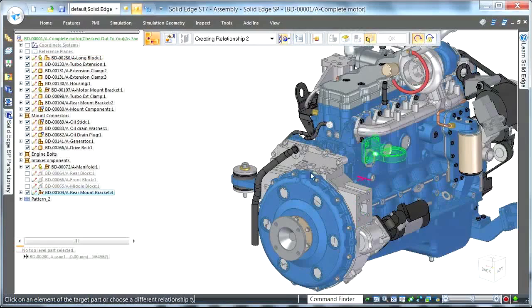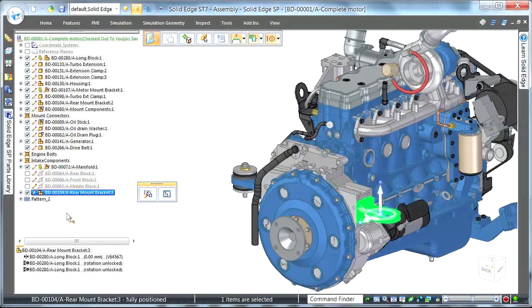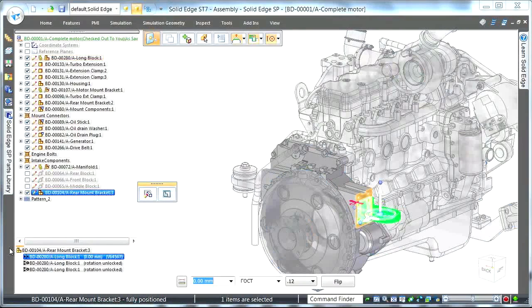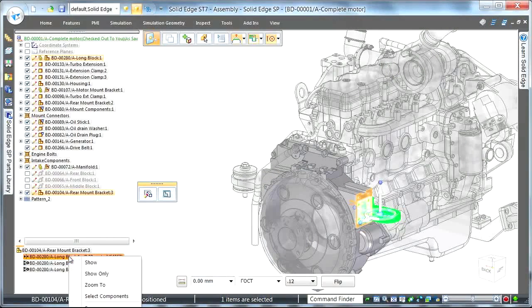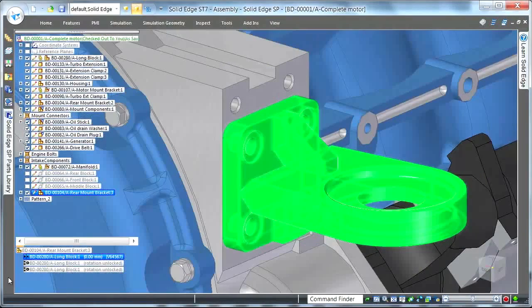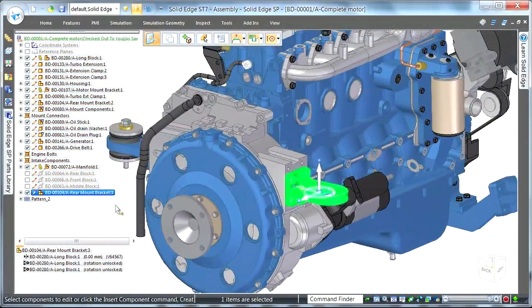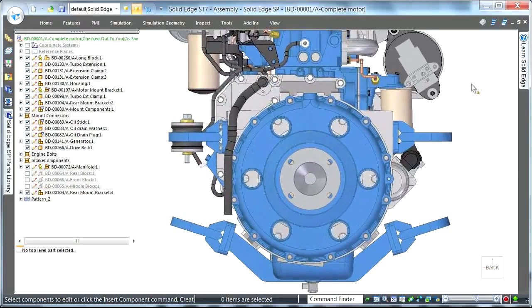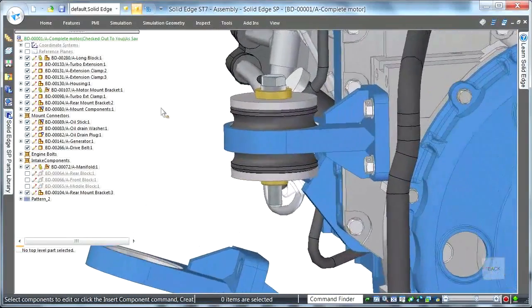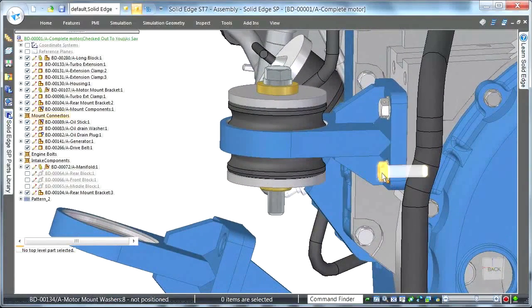All right, so we'll get hold of the component that we require for this. Just before we do, it's worth me pointing out some other things. So we have obviously the quick way to snap components into position. You're used to that, being able to build in the assembly relationships with that component as you drag it in. But something new in ST7, as we click on those assembly relationships that are created, do you notice it's ghosted all of the components, apart from the ones that we're dealing with in that assembly relationship? Just gives you clarity on what you're working on. You'll also notice there's some more right-click options as well. So if we wanted to zoom to that assembly relationship, it'll take you straight to that area in the assembly. It's all about this user interface, all about ease of use.